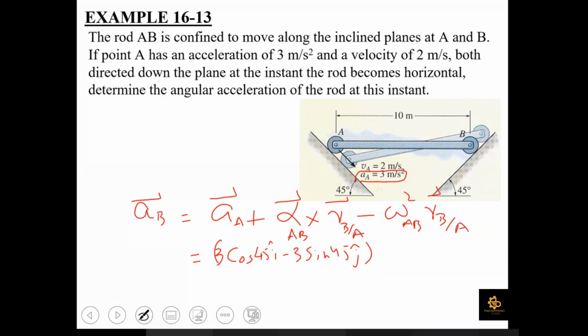Tangential axis. It is the angular acceleration of link AB. अच्छा, अब angular velocity तो आप कुछ common sense के साथ judge कर सकते हैं, but can you judge कि ये angularly accelerate हो रहा है या decelerate हो रहा है? Can you judge it? No, sir. So if you cannot judge it, you are always going to assume it in a counterclockwise direction. Solve it. If the sign of alpha after solution comes out to be a positive quantity, that means your assumption is correct. If it comes out to be a negative quantity, that means you are going to reverse your assumption.